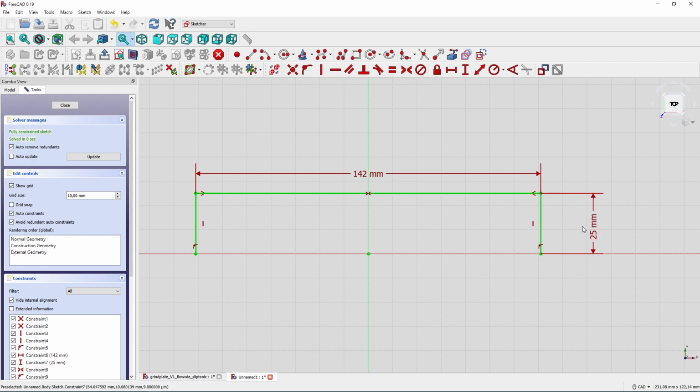Next thing I want to make is to create a radius down here for the grind area. So I click on endpoints arc, select these 2 points here and define the arc. Now we need to define where this center point of the arc is located. Just glue it on the vertical axis: center point, vertical axis, fix point onto object, and we're fine.